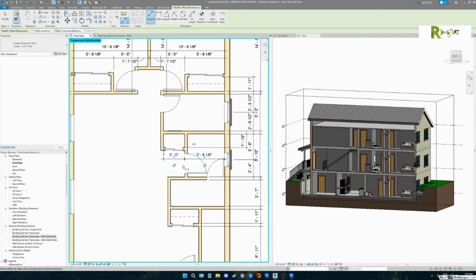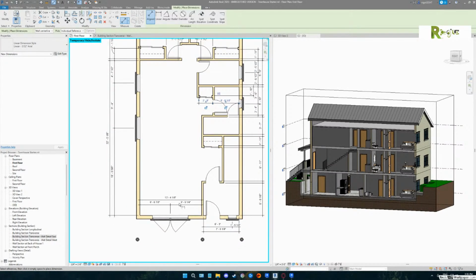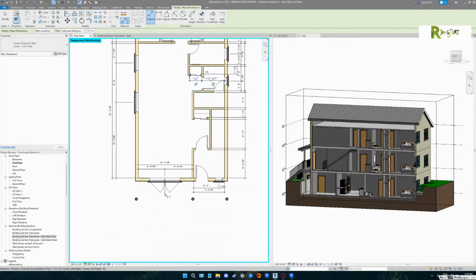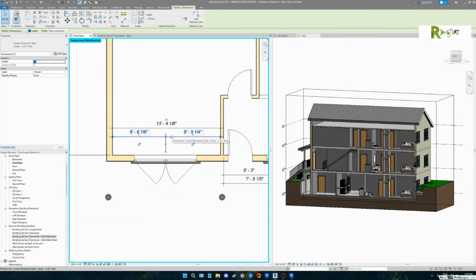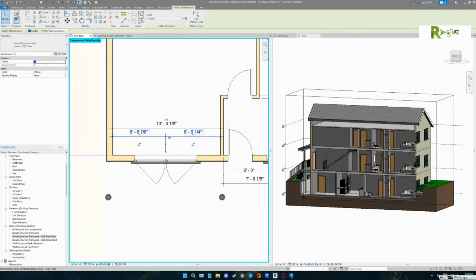Yeah, I think I was really afraid to put my dimensions on the inside. I only did it right here because there was nothing there at the time. And that's an exterior. That should actually be on the outside because you're dimensioning the window, which is on the outside of the building. Now this is to wall, so that would stay on the inside, right? Yep, correct. And the window would go to the outside. There, you just drag that witness line. Oh yeah, I see. Okay.